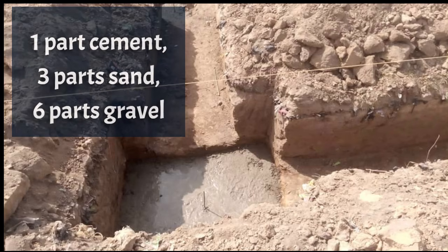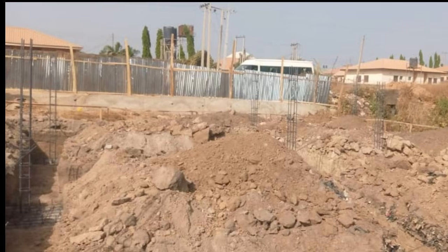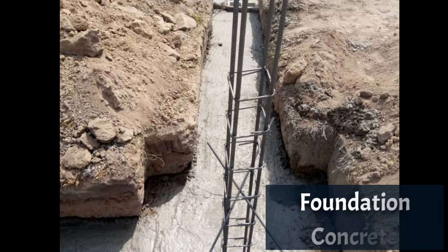After the blinding, the reinforcement baskets are now placed in the column base. Apart from the baskets, which are also called mats, the column starter bars are properly positioned in preparation for concrete work. Once the reinforcement bars have been placed and checked, the next item of work is the concrete casting.